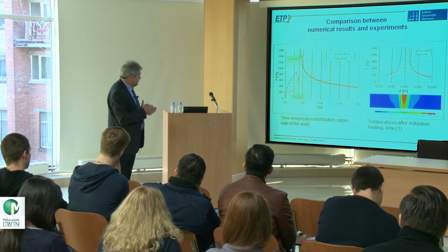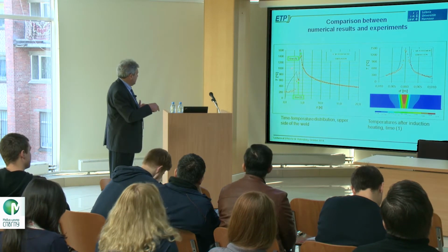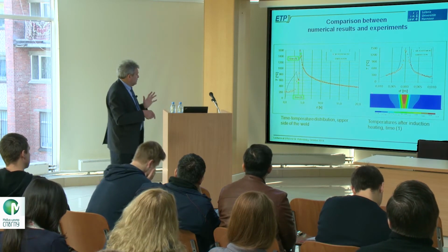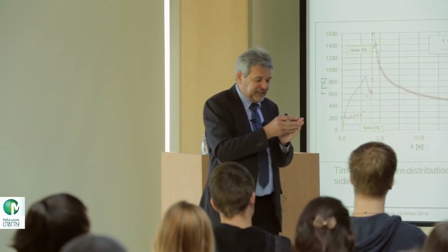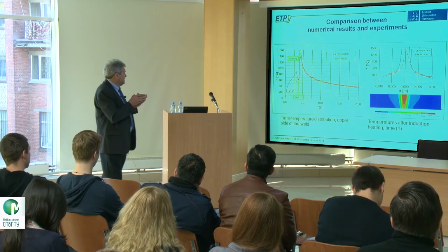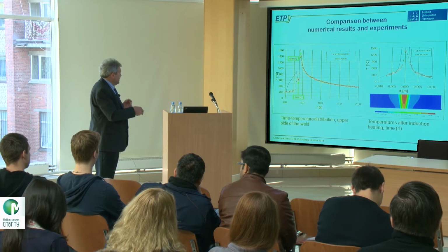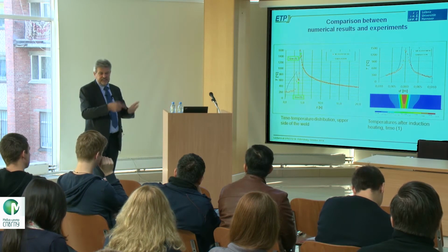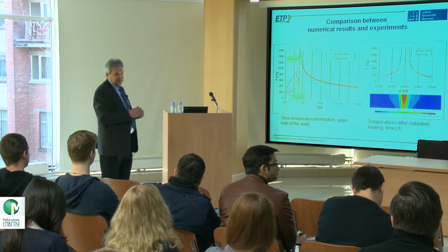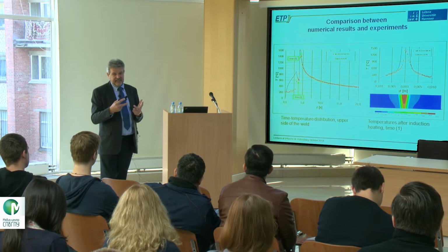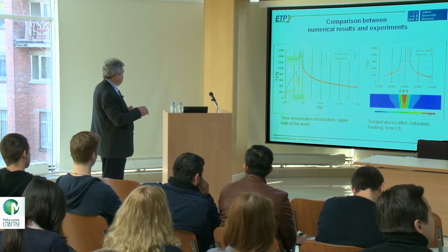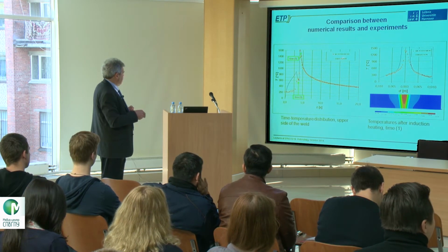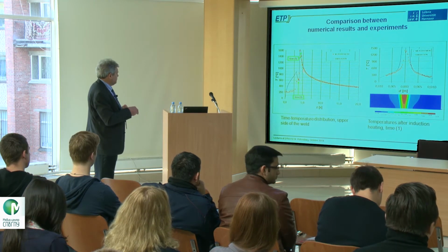And of course, you can imagine if you bring in by induction heat, which is wider than only the laser beam, the laser focus, then you need more time for cooling down because more heat is inside, and then you can increase this T85 time. And this you can do, of course, by preheating, as it is shown here, but also we investigated if you make a post-heating.